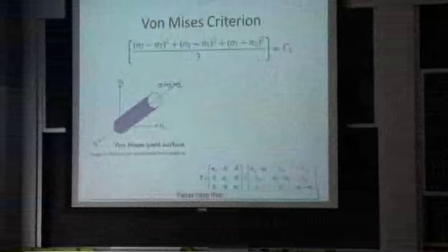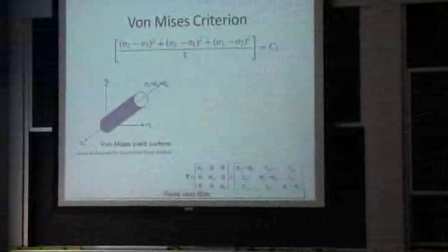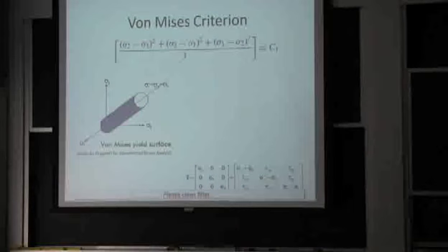The hydrostatic component will not cause deformation, and that's why we use hot isostatic pressing. Isostatic compression will not deform or change the shape of something. You can put a chess piece in a hot isostatic press, and it will come out shaped like a chess piece when it's all done. Unless you reduce porosity, right? Unless you reduce porosity. Right.